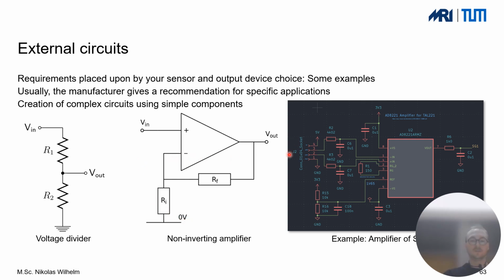I had just this problem 2 weeks ago when we designed a new force sensor. This force sensor has only a range of 3 millivolts, but the system wants to read something in the range of 2 volts. So we need a huge amplification of the respective signal.